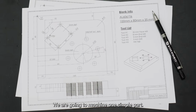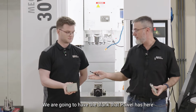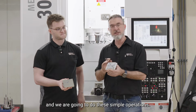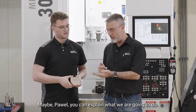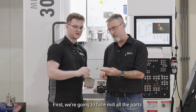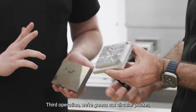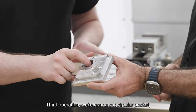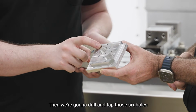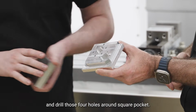Okay, we are going to machine one simple part. We'll have the blank that Paul has here, and we are going to do these simple operations. Paul, maybe you can explain what we are going to do. First, we're going to face mill all the parts. Second, with the same tool, we're going to cut the contour. Third operation, we're going to cut a circular pocket and a square pocket. Then we're going to drill and tap those 6 holes and drill those 4 holes around the square pocket.